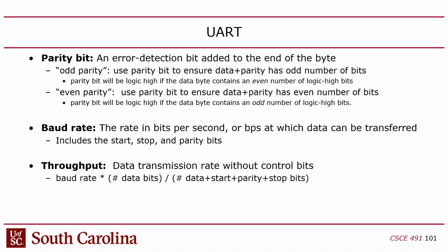I appreciate it. So with UART, you can have a protocol that sends text essentially, right? And some drones will actually do that. You'll have a text-based interface where the flight controller can send commands to the drone, or to any kind of robotic type application, and just tell it what to do in ASCII essentially. So you could literally print a string. In other words, you do communication by way of ASCII strings.